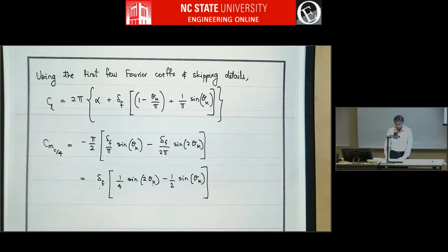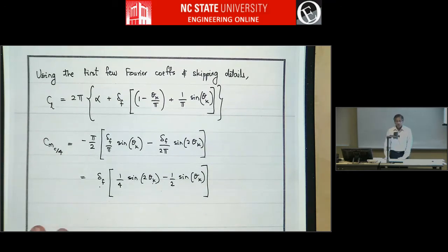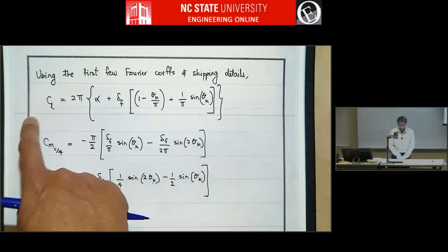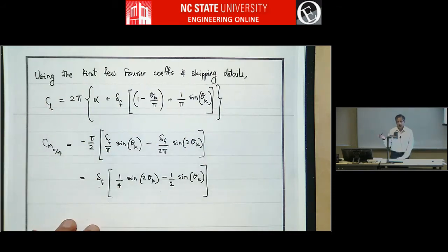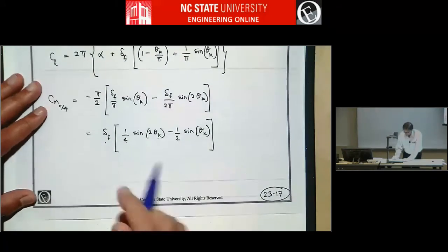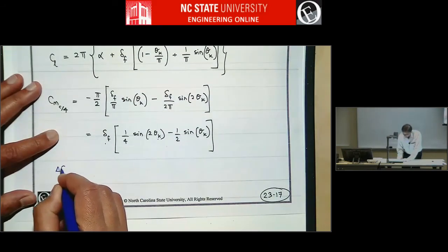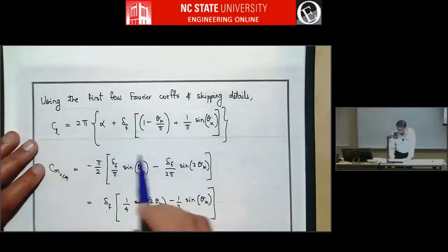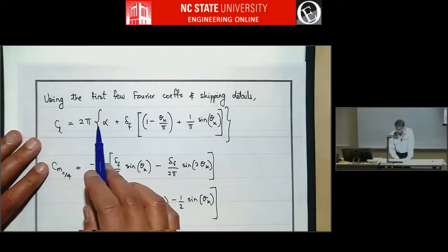So if you want to find out what is the effect of a flap deflection on a cambered airfoil, you can just take the delta from this and add it to the camber condition. So you can say from this delta CL, for a symmetric airfoil, CL is 2 pi alpha, right?